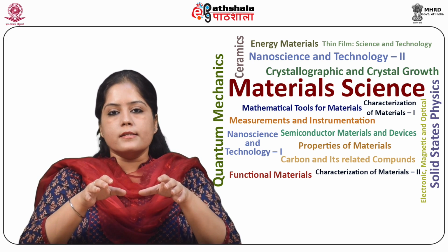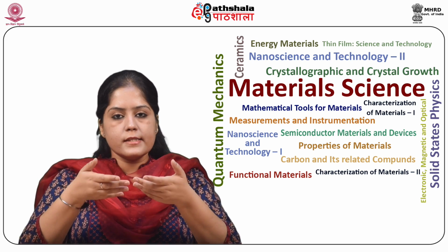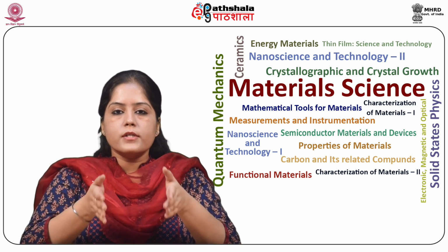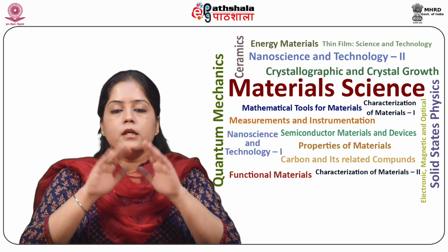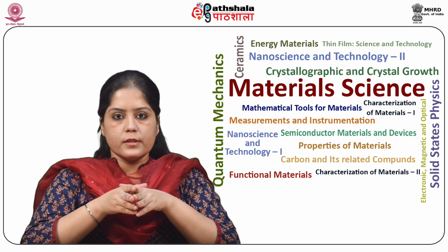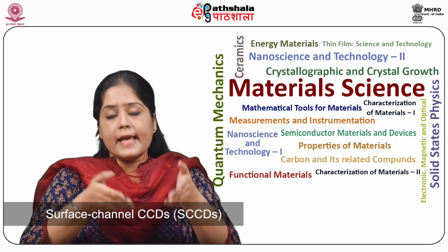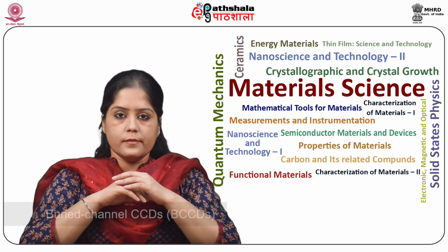Now various dies are fabricated on each wafer, tested and packaged into a ceramic or polymer casing with a glass or quartz window through which light can pass to illuminate the photodiode array on the CCD surface. CCDs can be fabricated as surface channel CCDs, that is SCCDs, and buried channel CCDs or BCCDs.